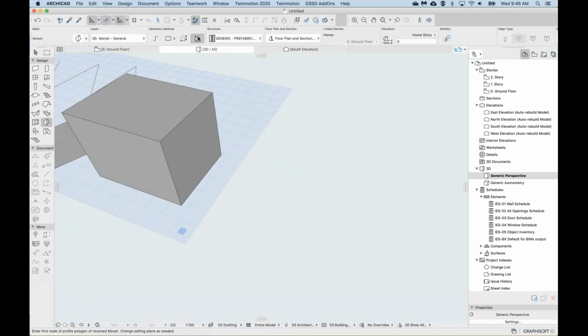The revolved is not really parametric, meaning you can't just modify the shape of the profile and have it revolved again. So it becomes a kind of permanent shape, which you can edit as just a blob after you make it. When we use the shell tool later, we can see that this is more parametric, meaning that we can change the revolution, we can modify the profile along that revolution, etc.